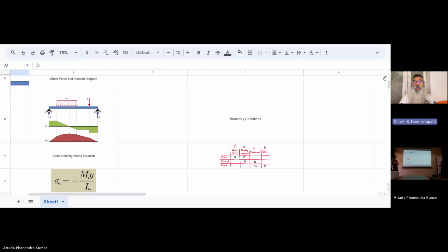So that comes under kinematics. Whereas you can have boundary conditions in terms of the load, where you're applying the load. For example, in a cantilever at the free end, you're applying, let's say, a load. So that becomes a boundary condition, which is part of the equilibrium equations. So you split the boundary conditions into two. Those which are meant for the equilibrium equations are called natural boundary conditions, and those which are meant for the geometry, which come under kinematics, are called the geometric boundary conditions. Okay, yeah, that makes sense.